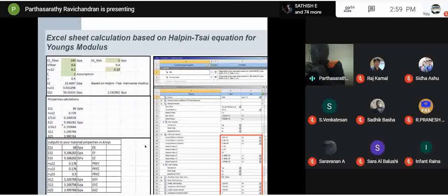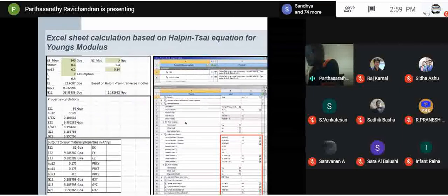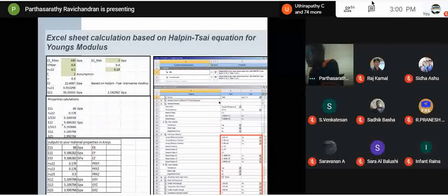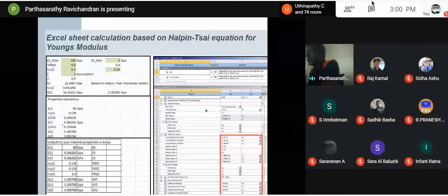In this slide, you can see on the left-hand side the actual calculation based on a spreadsheet, how it would look and how you can put those parameters into ANSYS or any finite element analysis technique. In this case, the engineering material for elasticity is struck off because we took the orthotropic elasticity material, where we were able to transform all these properties, and we have to make sure the density of the material is for the glass fiber, not for the steel.